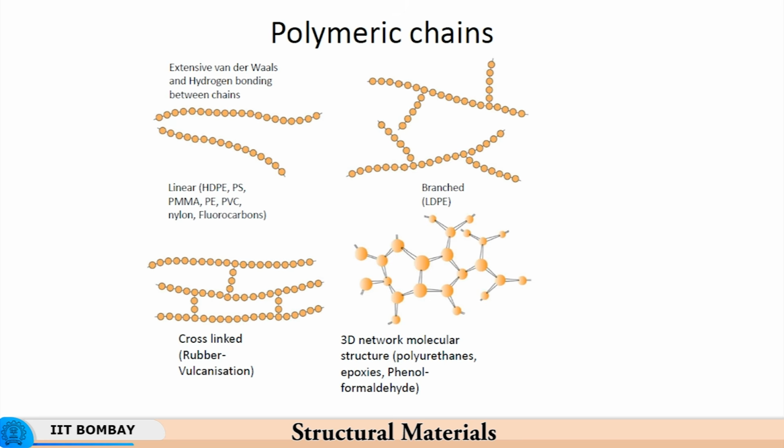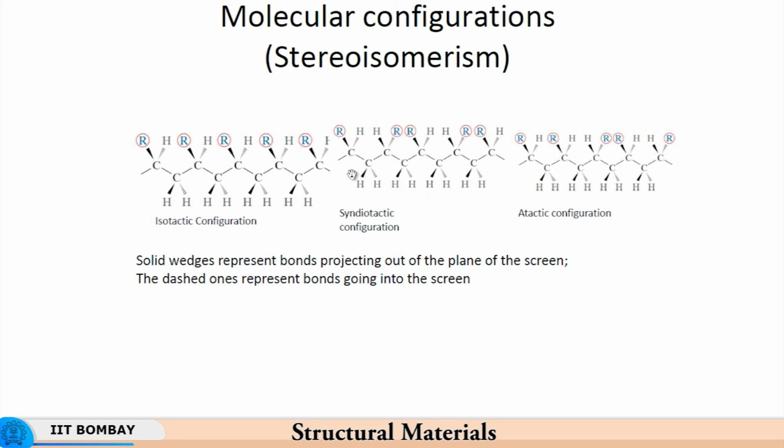Now here what happens is the extent of deformation is completely recovered, and this recovery takes place immediately after the load is released, and so you have the component returning, or tending to return, to more or less its original shape. The original diameter tends to get recovered. Yes, there is a change in the layout of the chains, but you have alignment of the chains, but then there is a significant amount of swelling of the workpiece when it comes out of the extrusion die.